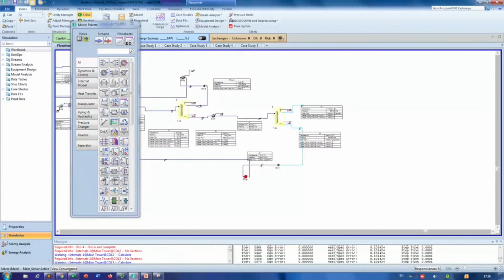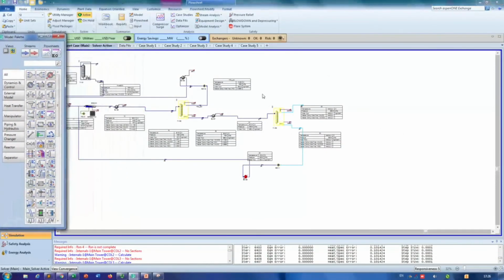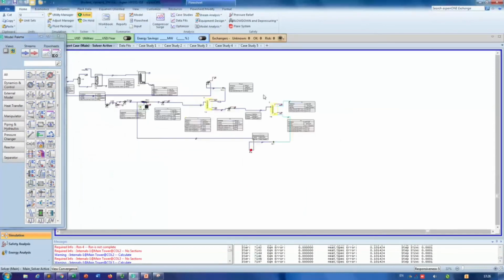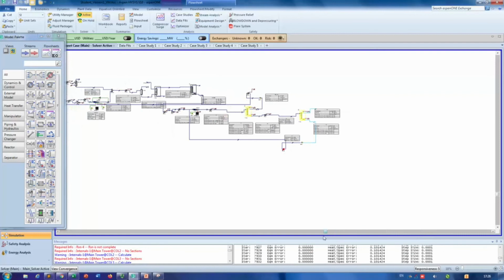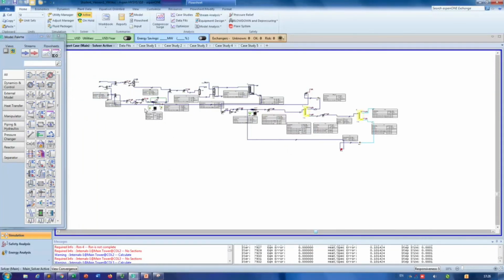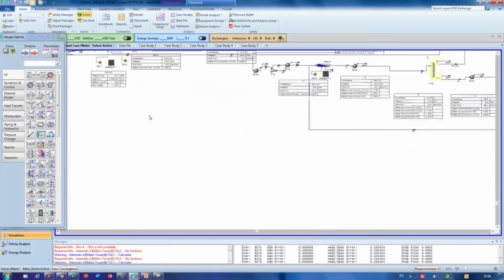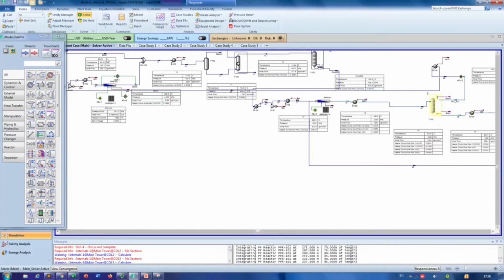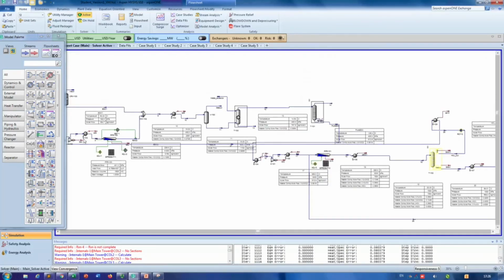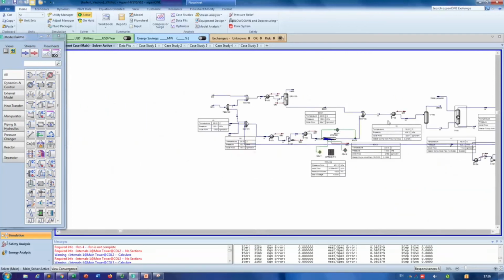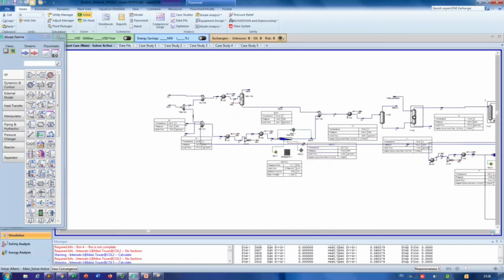If you see how our process flow sheet looks, it's a really massive one. We really managed to build such a big process flow sheet. So what we did is we did some direct chlorination and oxychlorination reactions. We take the ethylene dichloride and try to purify it to 99.5% pure.